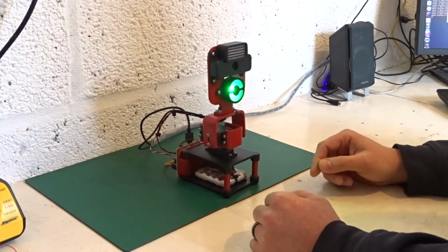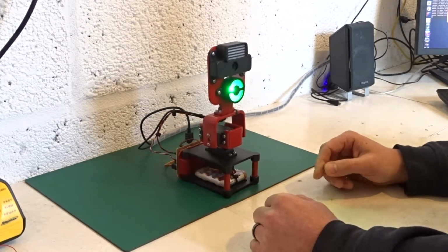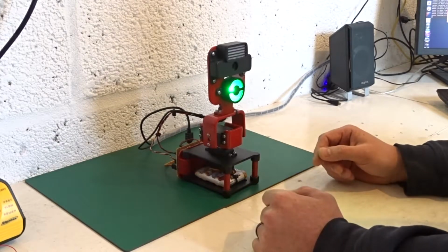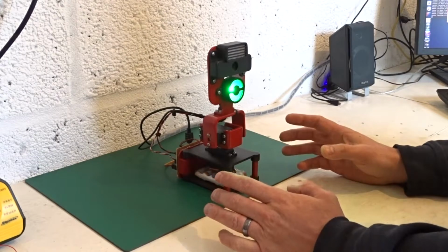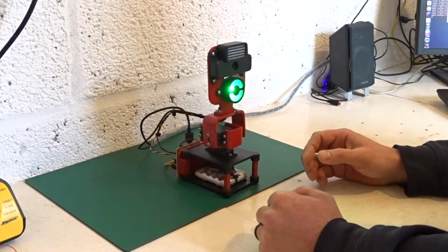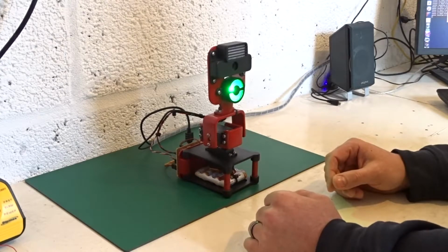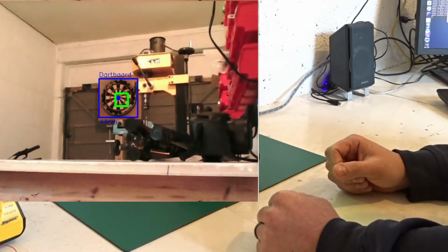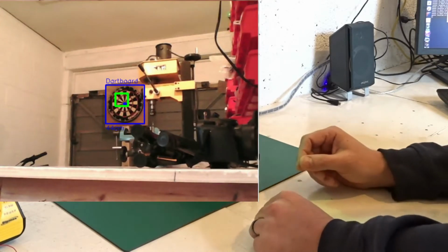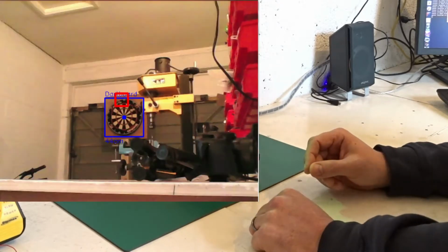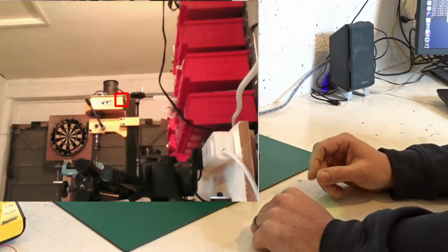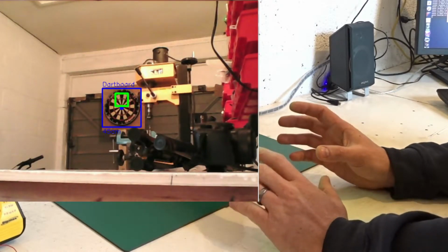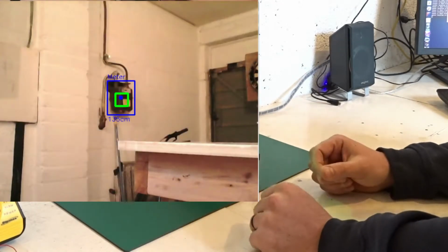To start this, I was just using proportional control, working out an error in the X and Y camera coordinates, and using that to drive the servo pan and tilt positions to try and centre the object in the field of view. So this worked to some degree, and the object would be almost centred in the camera's field of view, but the resolution of movement wasn't good enough for the object to be centred every time. If you have a look at some of these clips, you can see that working, and you'll see that occasionally the robot will stop and the object isn't fully centred.